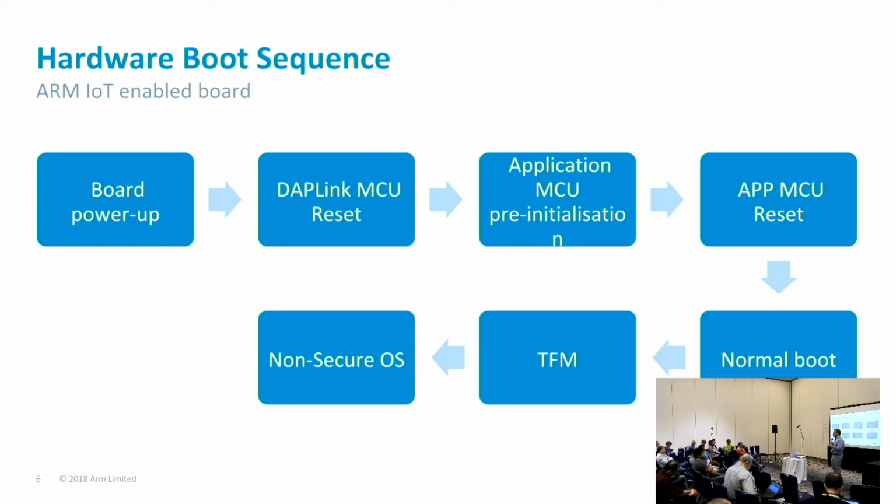Most of the tests that take a lot of time are those that are validating the secure storage currently, which is quite a complicated procedure because it's a set of unit tests that are doing writes and verifications. And to that, the speed of your flash interface actually matters. I'm just assuming that not everybody will use the same type of memory, and it's quite possible that will trigger some hard-coded timeouts. But it can be that some tests need to do things that last long. It depends upon what the test scenario is.